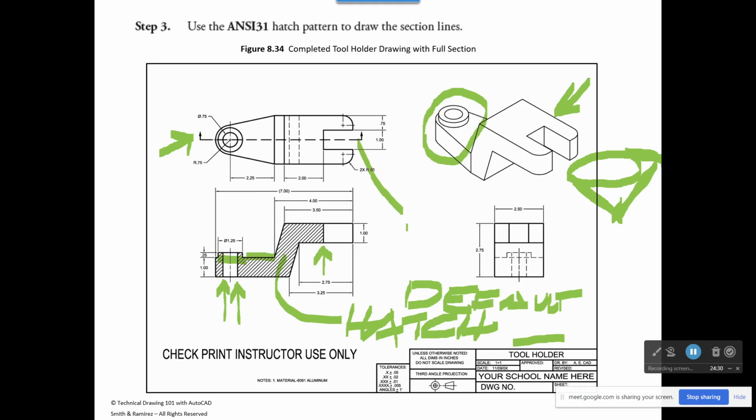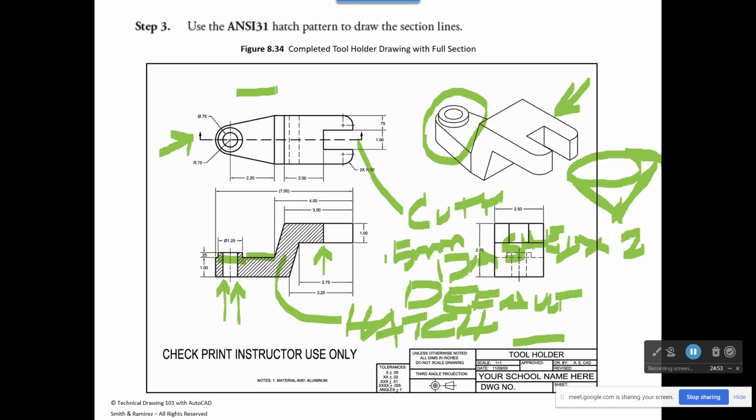And then you're going to also make a layer called cutting plane. The cutting plane layer you're going to set to 0.5 millimeters thickness, and the line type is going to be dashed X2. You've got a line type you're going to have to load. It's called dashed X, so it's like times 2. What that gives you are these long dashes that are longer than the dashes in hidden lines. And because we're setting it to 0.5 millimeters, it's going to be a heavy line. All right, so that's your first assignment.